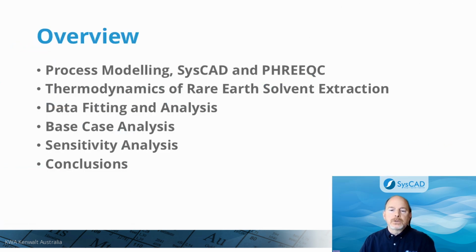Our presentation includes an introduction to process modeling with SysCAD and PHREEQC, the thermodynamics of rare earth elements solvent extraction, thermodynamic data fitting and analysis, sensitivity analysis through modeling and analysis of additional cases, and conclusions.